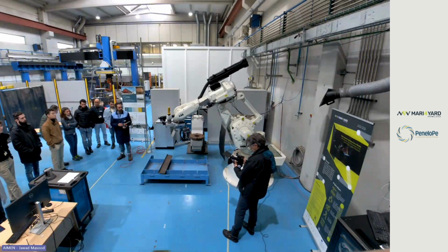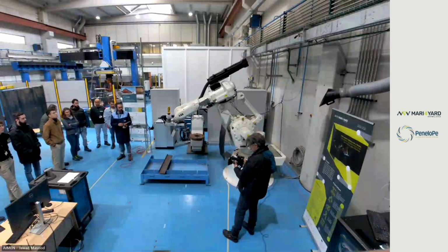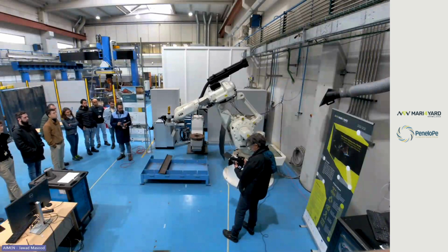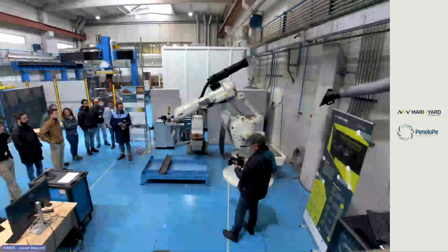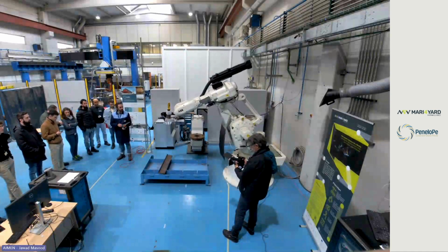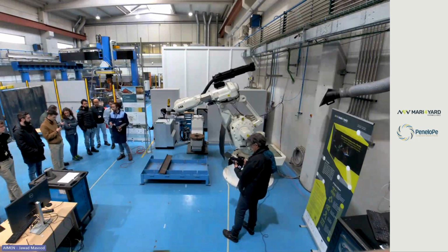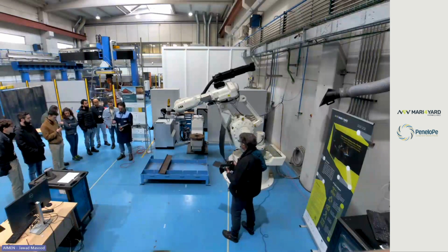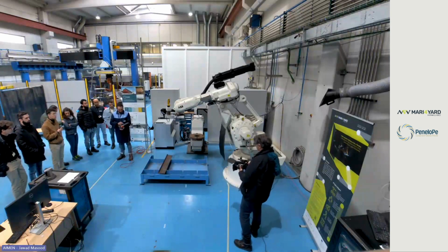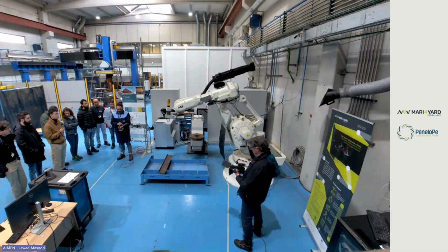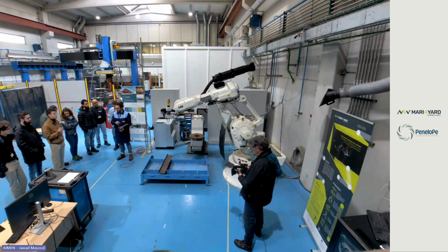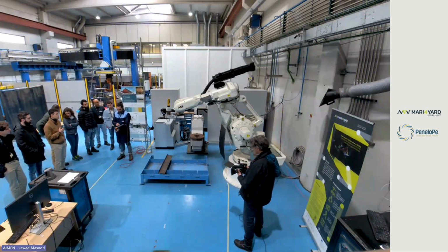I'm going to put the robot with that orientation. And for example, let me go up, maybe. This is, for example, a good home position outside of the part. What I have to do now is push save to save that position on the point P home, okay, and that's all.